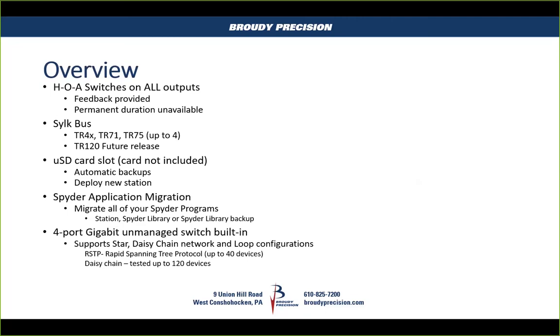They call it the diameter. So you could have 40 devices in a loop, and if you cut the patch cable between 2 of the controllers, or you turn one of the controllers off, the rest of the controllers will still talk because of it being a loop. It has another path going back. And that's for up to 40 devices.